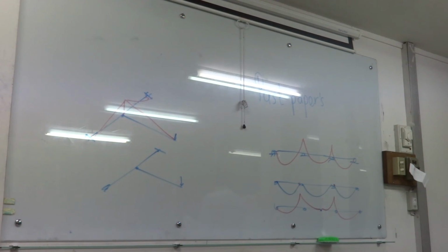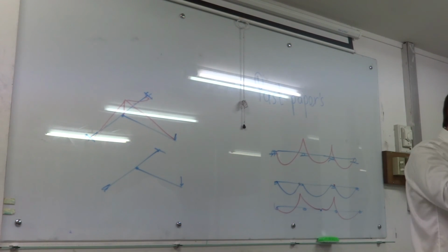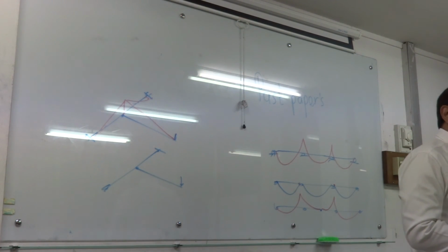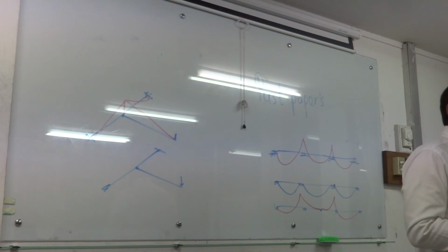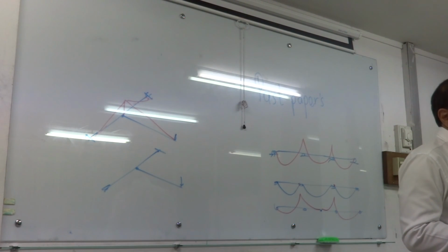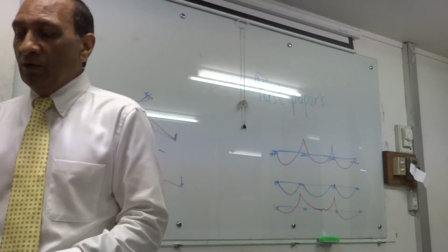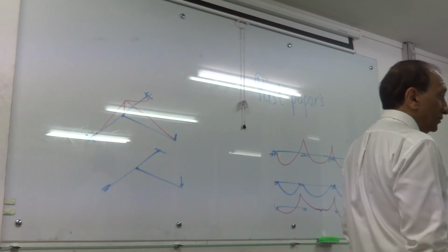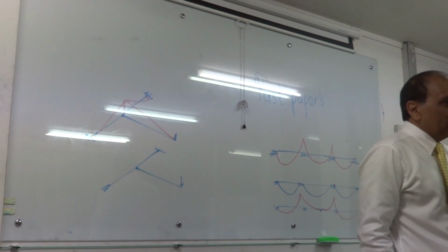If the structure's compatibility torsion is coming from indeterminacy, then it is a compatibility issue, and you can choose to reduce the torsion capacity or ignore the torsion and produce artificial hinges to neglect the torsion design. But if it is a determinate structure, it is a stability problem. You cannot neglect it. You must design it. So many engineers choose not to design for torsion in case of compatibility, or they choose to reduce the torsion to 25% or 10% of the actual value, because the real compatibility torsion is too high, and it is not correct also. Why?